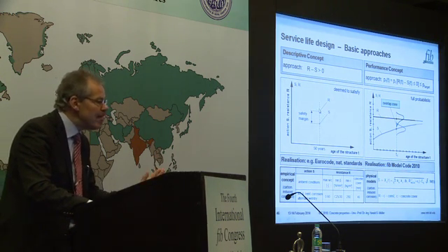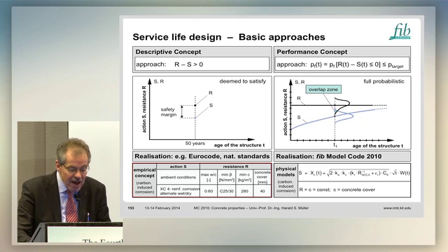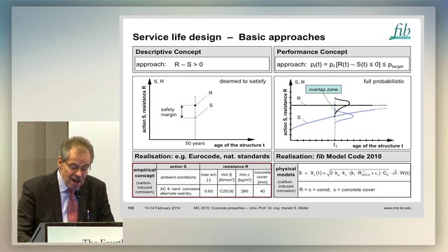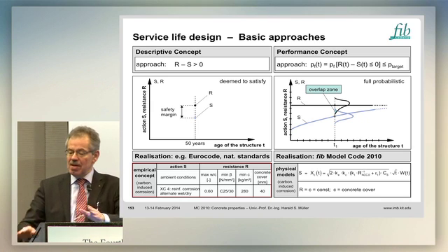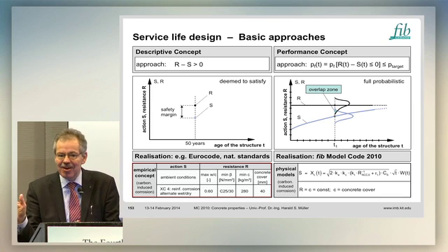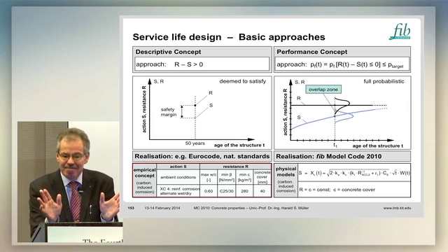It was our experience. And this experience you find given, for example, for certain ambient conditions. We said, okay, if the maximum water cement ratio of the concrete is 0.6, minimum strength C25, minimum cement content, and the concrete cover is 40, then this building withstands the actions of the environment over 50 years. No possibility to calculate anything, just feeling.